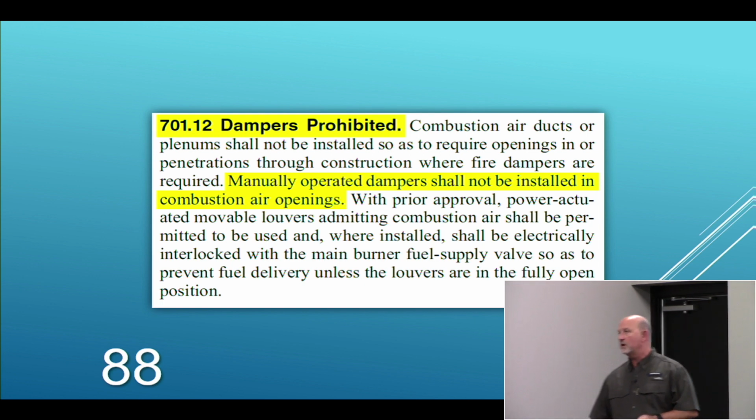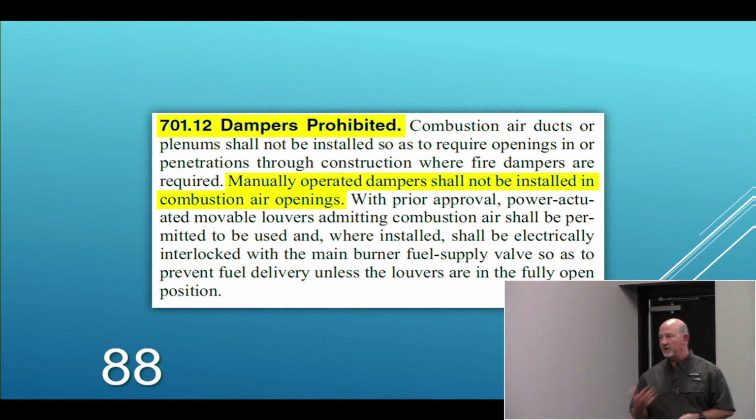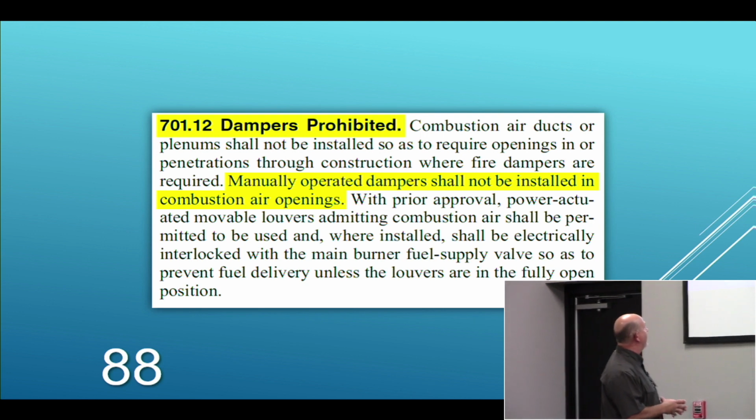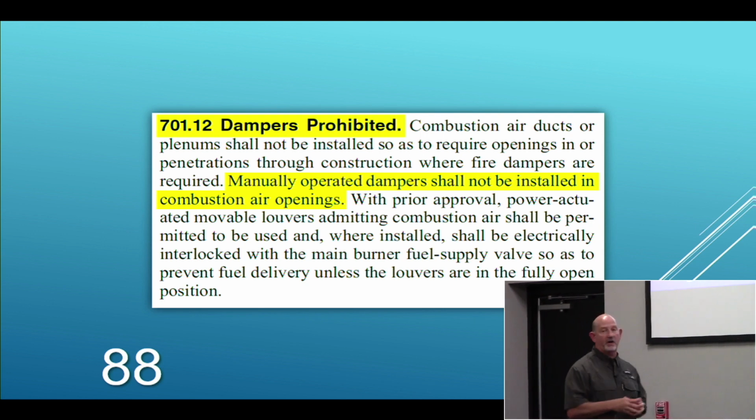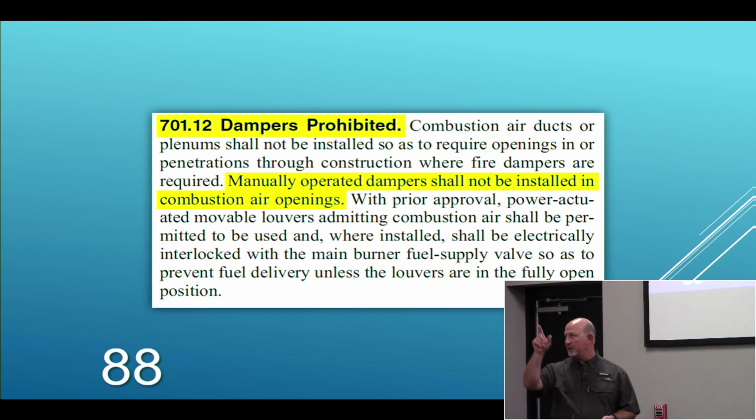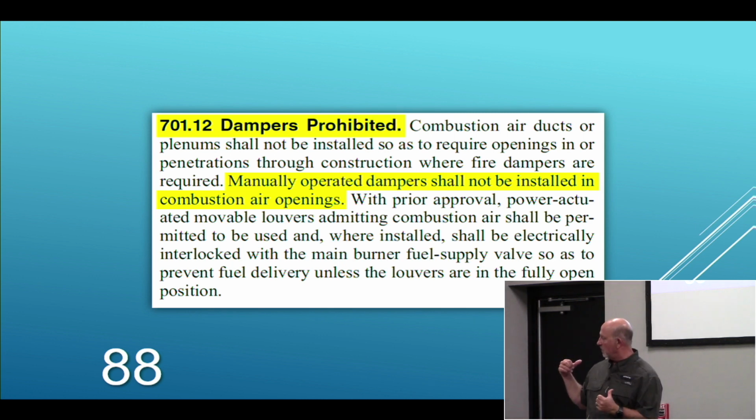Yeah. So now again, the theory here is, notice what this is saying. Manual operated dampers shall not be installed in combustion air openings. So whether that's an opening in that wall or an opening to the outdoors or an opening in a duct, vertical or horizontal, do you agree all those are openings?